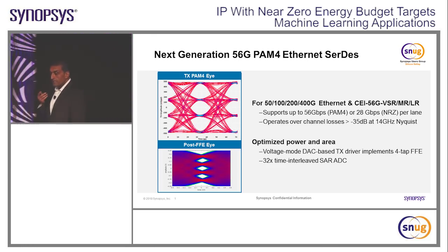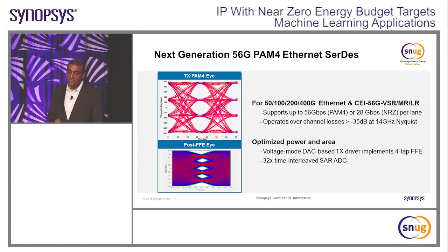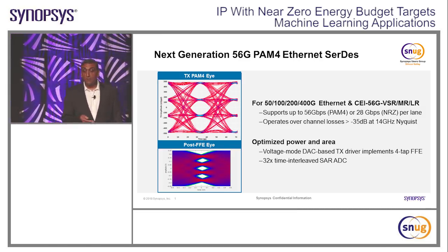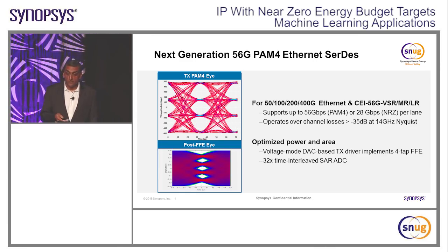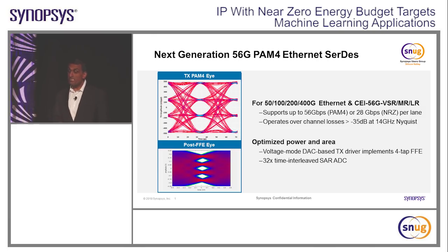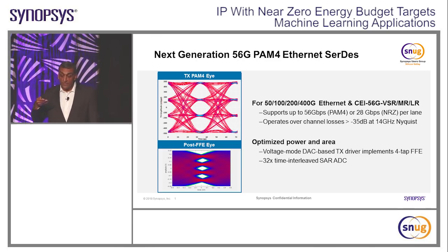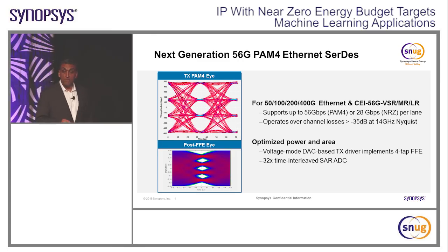Okay? So the key points in this section, just to recap, is that the data center and enterprise are both bifurcating into two markets. The data center is pushing bandwidth, enterprise is pushing energy consumption. The ways to reduce energy is to look at energy efficiency on your MAC layer and to implement a low-power PAM4 SerDes.